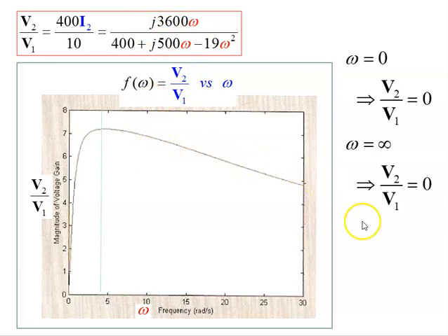But then we could still find the frequency at which we get a maximum and plug that back in and get our maximum value. So additionally, we've introduced in this video the concept of a transfer function and voltage gain, which we'll also look at more in further modules. However, notice what we've done here is a frequency sweep. A frequency sweep is something that we also do in PSpice. Typically what we've done up to this point is plug in a specific value for frequency, but if we want to do a frequency sweep, then we have to consider our inductances j omega L and our capacitances 1 over j omega C for their impedances. So that's all for this video.